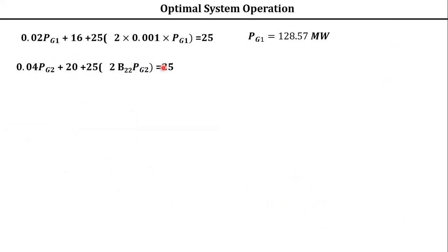So this entire term, instead of showing all this expansion and substitution, is not required. Generally, by common sense, looking into the network given, plant 2 is not contributing any losses. So in the coordination equation, the term corresponding to transmission loss will not be there. Therefore, dC2 by dPG2 is equal to lambda. That's all is your criteria. So you will get PG2 is equal to 125.